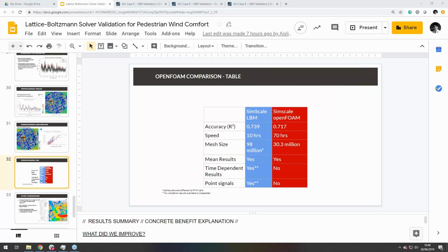So, for example, if we had a Reynolds number of 1e⁶, your wall refinement would have to be very, very fine. And if you got to the point where your mesh was 300 million cells large, it's going to start becoming quite costly for you. However, it could be a simple geometry. If it's a simple geometry and not an entire city, as this case shows, then that might become more doable. And also we could use the detached eddy model simulation to reduce those wall requirements and help you solve a higher Reynolds number.